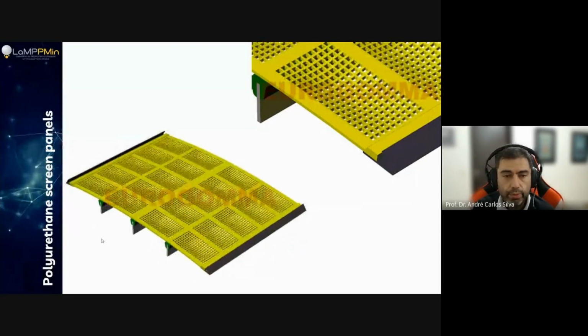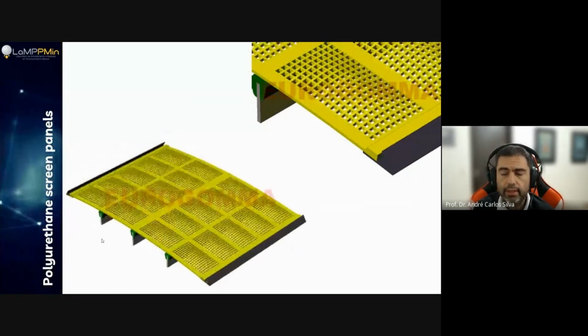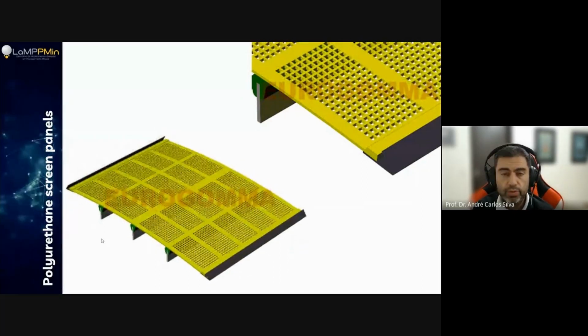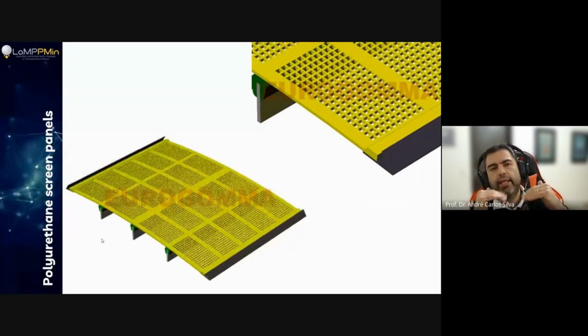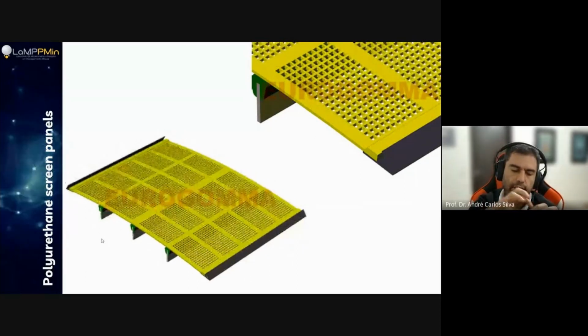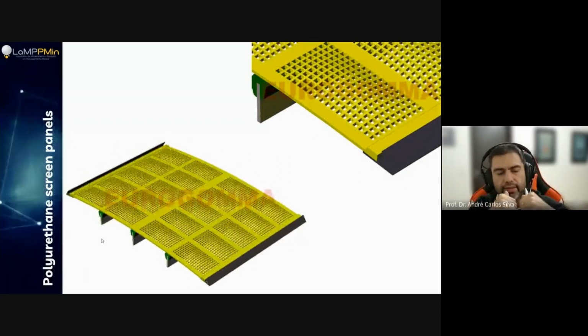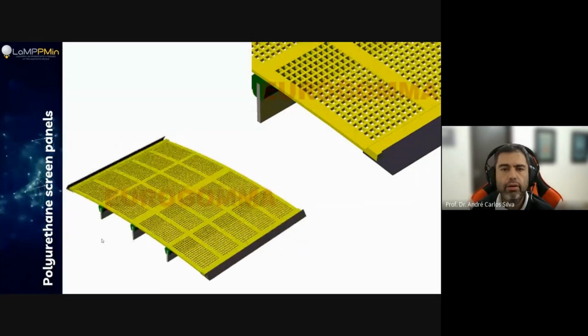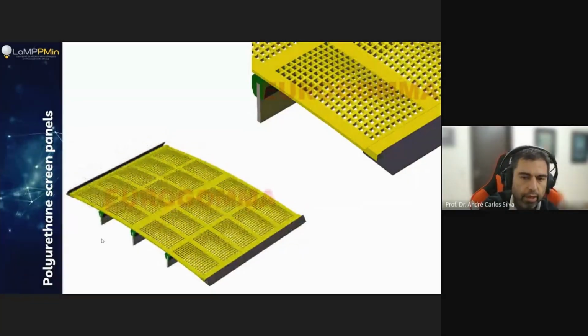But we can use rubber, we can use steel. There are other options. The polyurethane is quite nice because it's strong, it's quite reliable, it's resistant, it's a tough material, it's an engineering material. And actually it can bend, okay? So if you have a material that is clogging your apertures, your screening, by this movement and by this deformation, this bending of the panel, it's going to be released, and then you don't have this problem anymore.